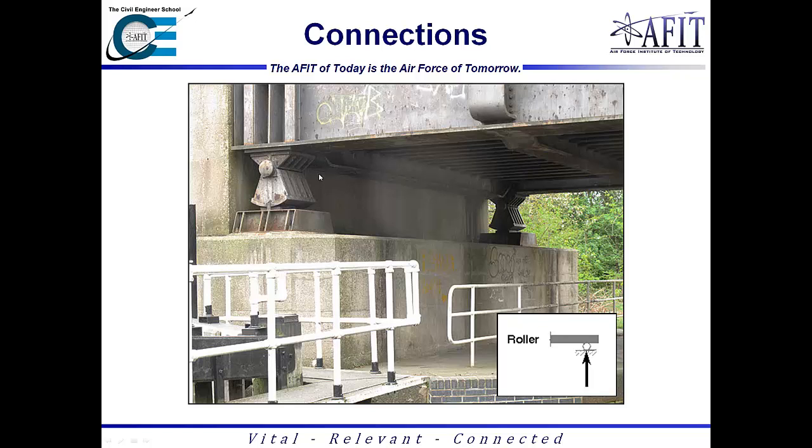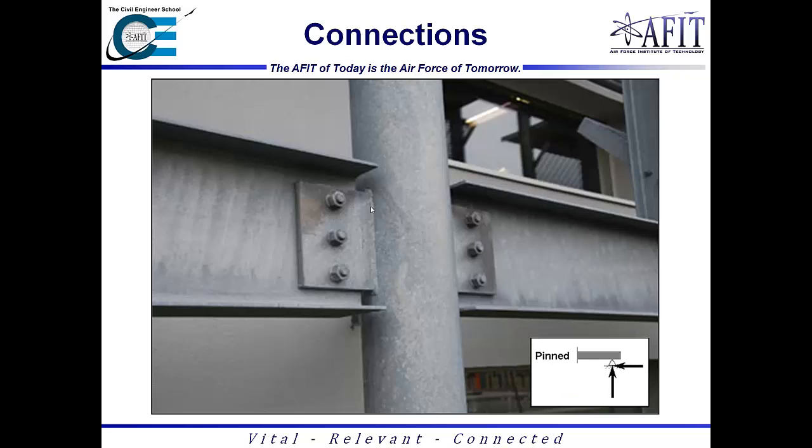But for resistance in the lateral direction, we have to look at what we call a pinned connection. With a pinned connection, as you can see here in a real world example, there's lateral resistance as well as vertical resistance. But there is no moment resistance here, so this member could actually freely twist if it needed to about the axis.